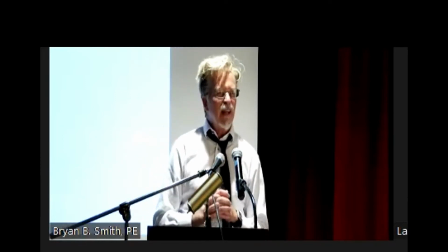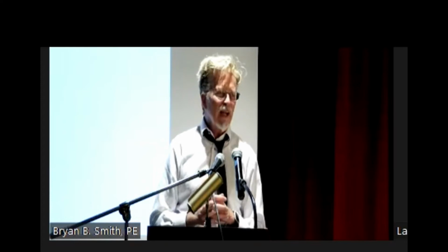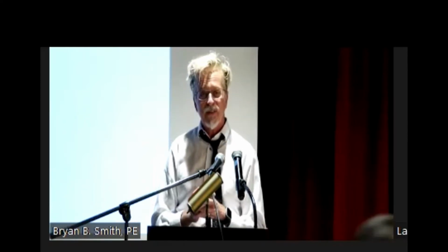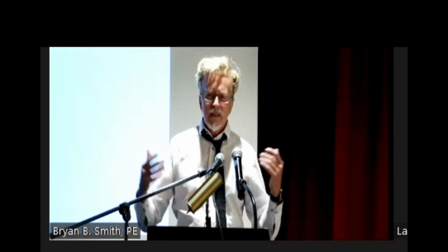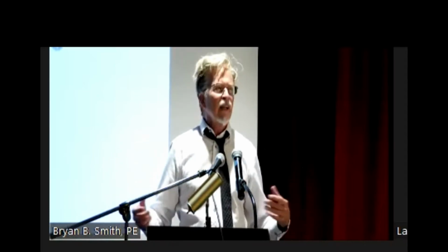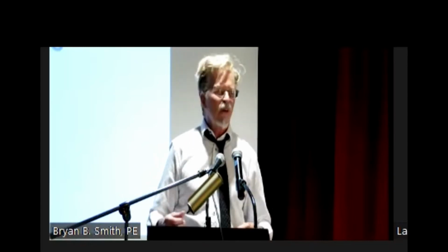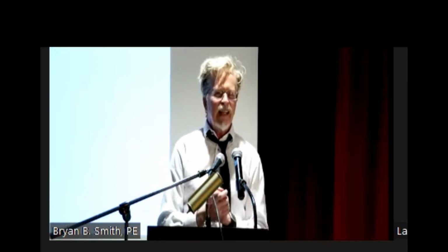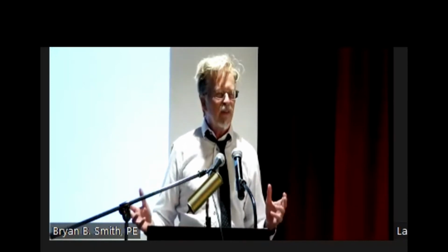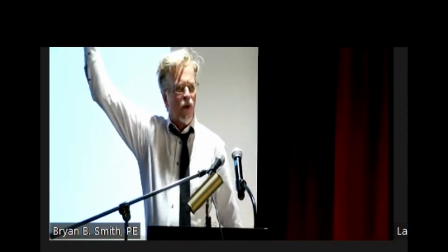What we're going to cover today is how this applies from an engineering standpoint. Most engineering firms are looking at steady state flow. What is my pressure when I kick on my pump? Is my pump pressure, flow, everything set? But it's in steady state. Steady state is like everything working perfectly. Now, who lives in a perfect world? Oh yeah, there we go. But in reality, it's like, wait, somebody just closed the valve.